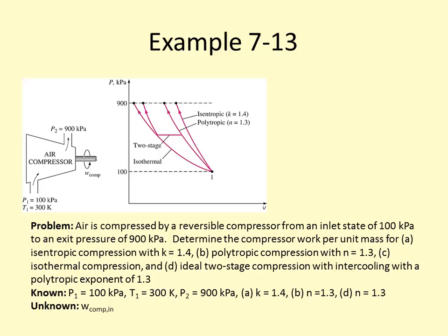So when you find R in terms of BTU per pound mass Rankine, you may need to convert it to psia times feet cubed per pound mass Rankine when you use this equation. And in that case, it's 2.6805 psia times feet cubed per pound mass Rankine.